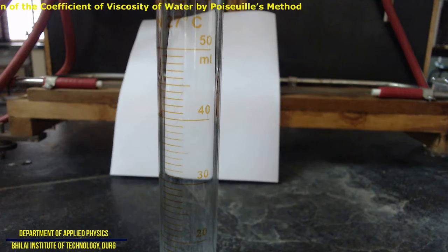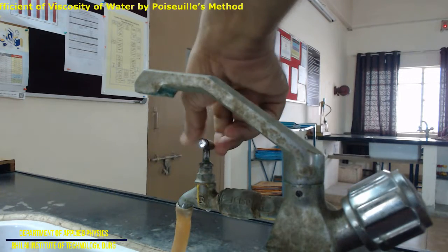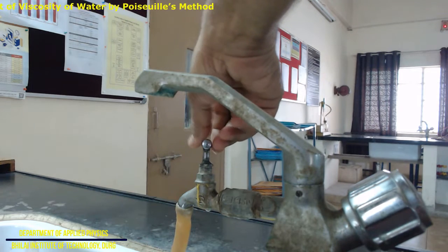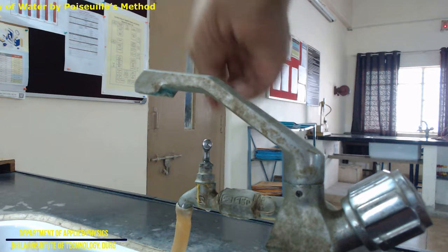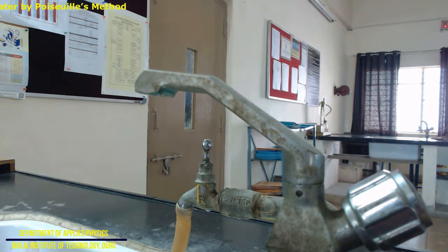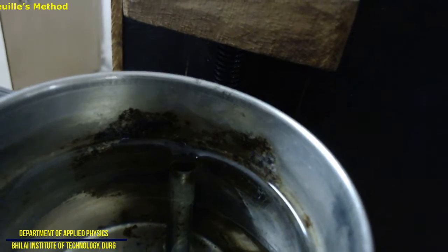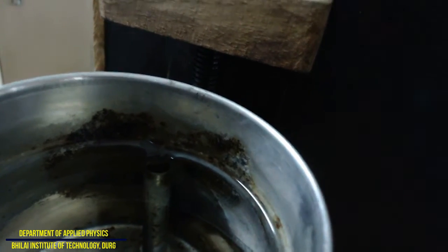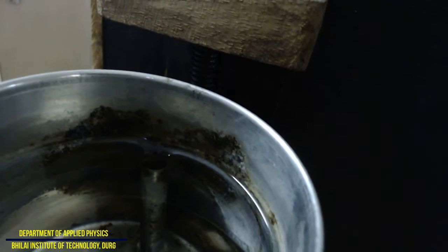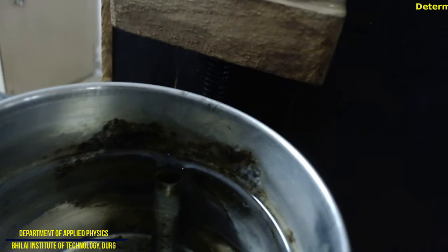Now we will learn how to do the experiment. First we open this bib cock to allow the water to come inside the tube, and we allow the water to rise up to the level of the overflow tube. This is the overflow tube, as I told you. Whatever excess water is there is going to come out of the overflow, and the level of the water in the tank is going to remain the same.